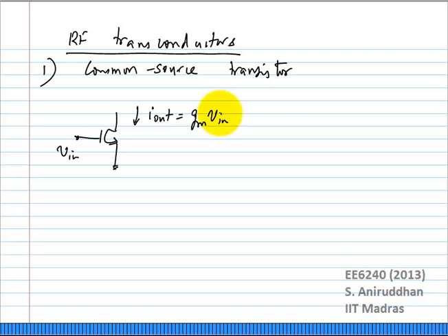On the other hand, the mixer comes down the chain. Therefore, its noise is less important, but its linearity is more important. So we need to look at those aspects first before we look at the noise. So how will you characterize the linearity of this common source? Again, what kind of linearity are we talking about first? Linear transconductance. Anything else?